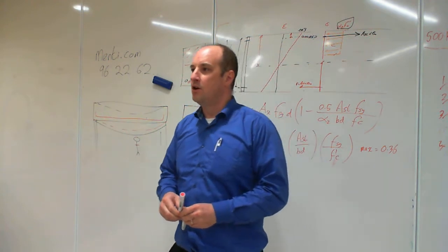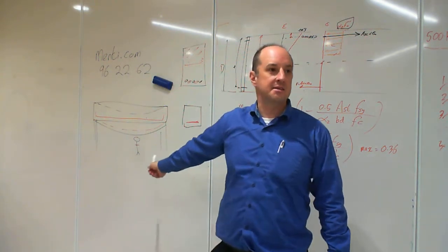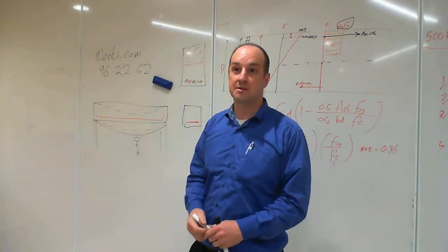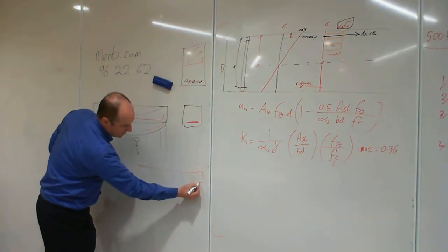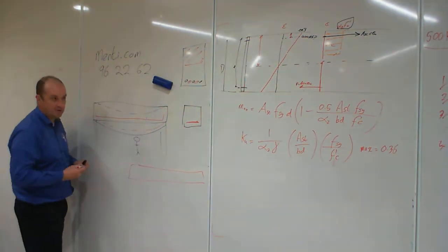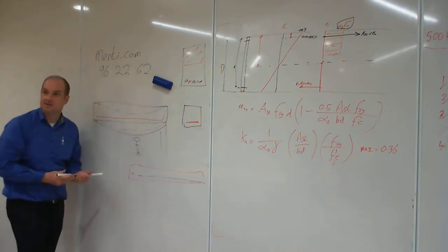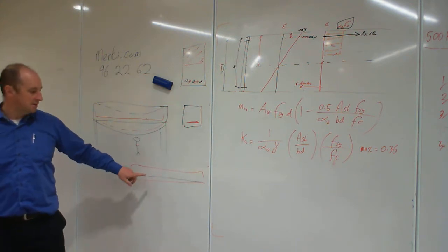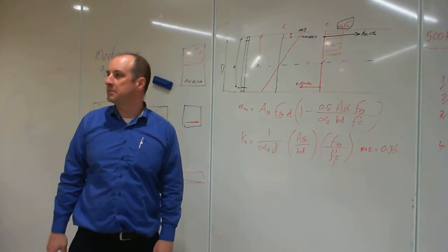Alright. While we're on beams, one-way slabs are exactly the same as beams. They're just very wide beams. In a slab, there's a slab there. You put your steel in the bottom. Again, it's the same thing, it's just a very wide beam, and without the rings. So one-way slabs, beams, you can use all the same set of equations, basically all the same assumptions.